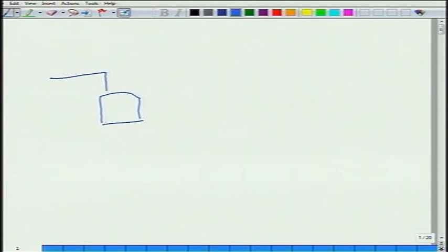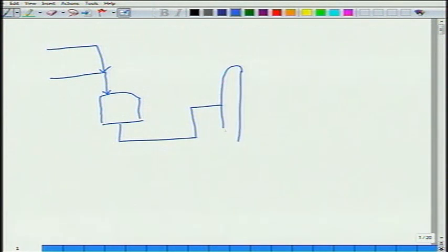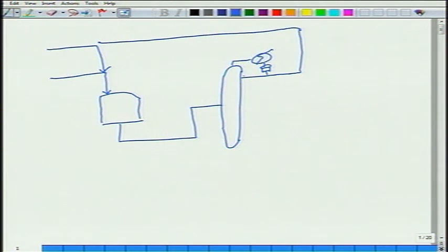we were trying to draw control structures for this simple process, one reactor, two column process. And we drew an on-demand control structure. We drew a control structure with the reboiler duty in the recycle column, which is the first column, as the throughput manipulator.